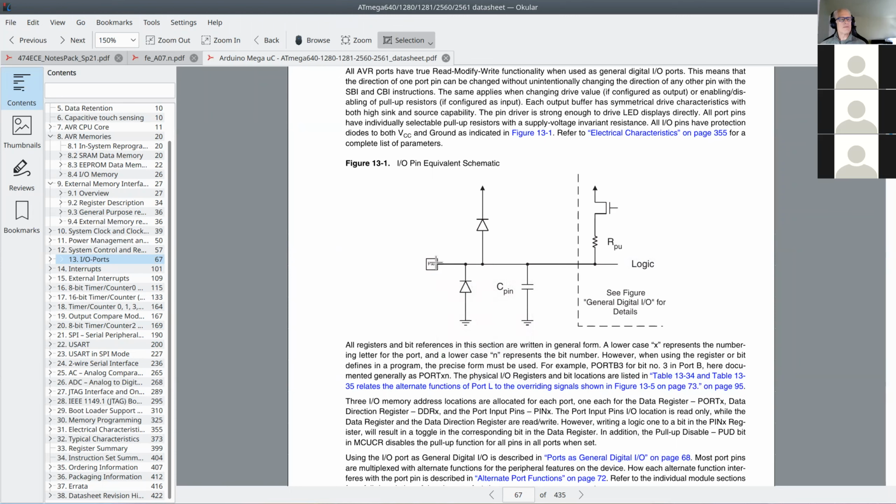And then what happens? Then we enable this pull-up resistor. So if the switch is open, the pull-up resistor makes a good quality logic 1 signal right there, and we read a logic 1, and we know the switch is open. If the switch is closed and this point is grounded, then current flows through the resistor to ground, and this point becomes logic 0.